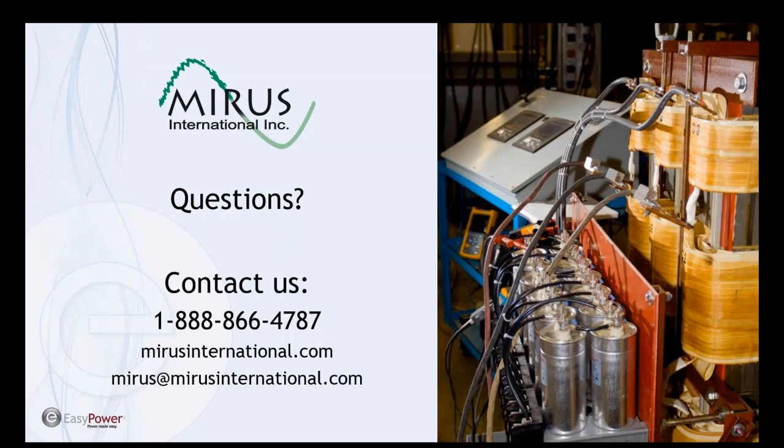Okay. The question is about utility penalties. Do they penalize for leading as well as lagging power factor? Yeah, typically the utilities will penalize based on a minimum power factor, regardless of whether that power factor is leading or lagging. Perhaps we should clarify that it happens at the peak. So if you're leading but under low load conditions, you wouldn't get penalized. Most utilities wouldn't penalize you for being leading in a very low load condition. That's right.